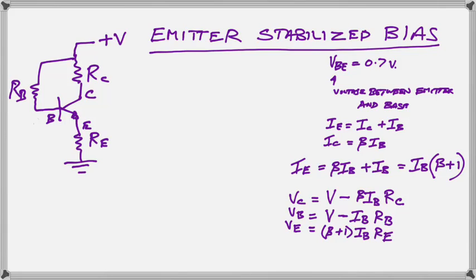If you notice, the only thing we have to find now is the base current. The base current is always the one that requires the most calculation. Now, as we can see, our system moves to 3 terms because we have to add the voltage across the emitter resistor, then we have to add the VBE, then we have to add the voltage across the base resistor. So 1, 2, 3 voltages as shown there.